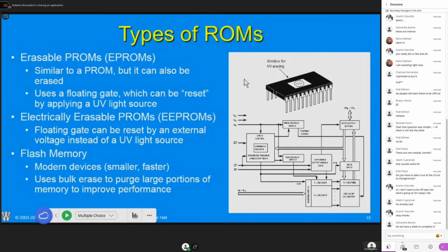So for example, to program a PROM in a 5-volt system, I might need 12 volts. But for an EEPROM, my circuit is operating at 5 volts normally, and I would just apply some signal, still operating at 5 volts, to erase or to set. So with electrically erasable PROMs, we just apply some kind of write signal that says, here, write to this place. So the circuit automatically erases it and writes to it for us.